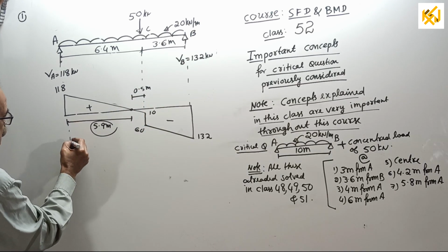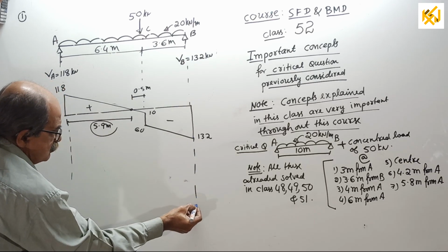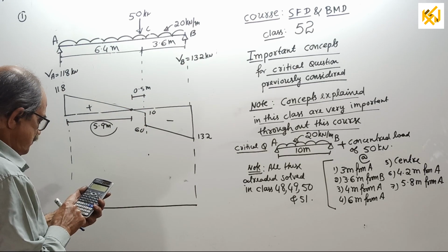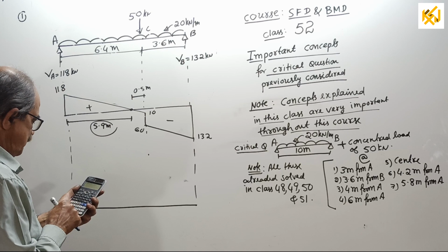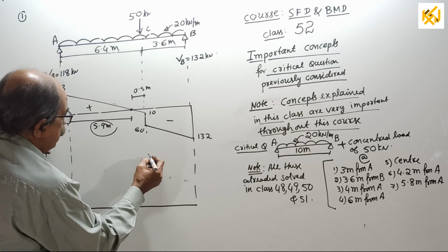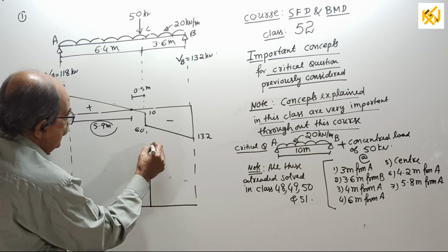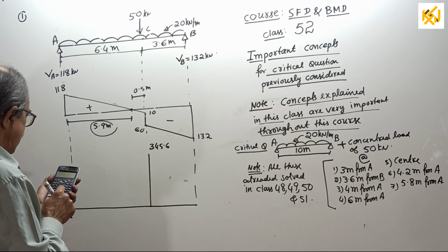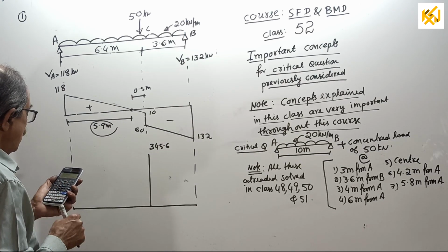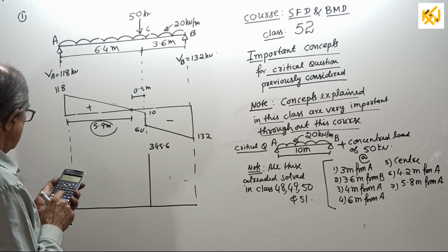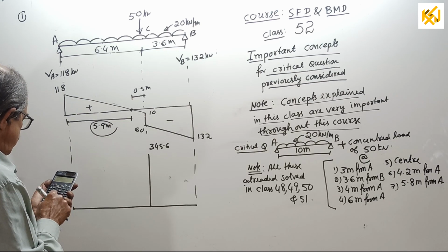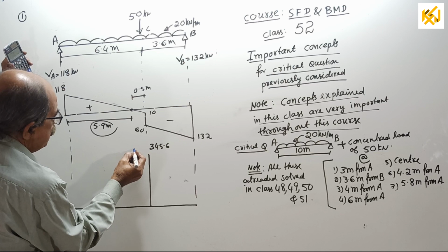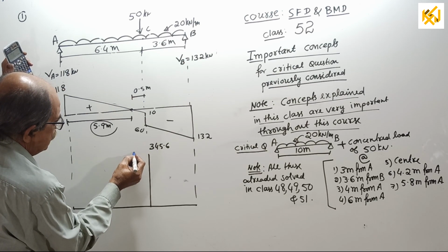Now, bending moment diagram. Observe now. Baseline. You need the bending moment here. 345.6 is the bending moment here. Here the bending moment is required. Directly I can get it, I don't require the location. 340, something wrong. 348.1. I got a doubt. 348.1, correct? I think a little more.